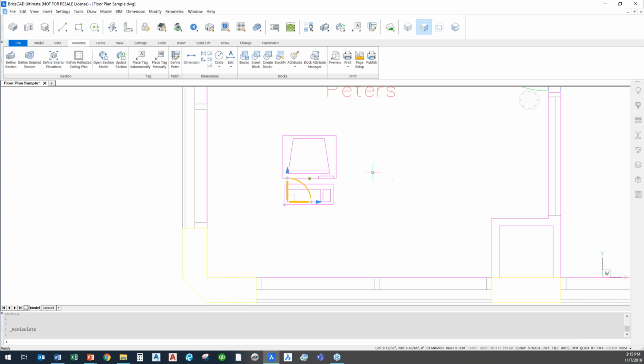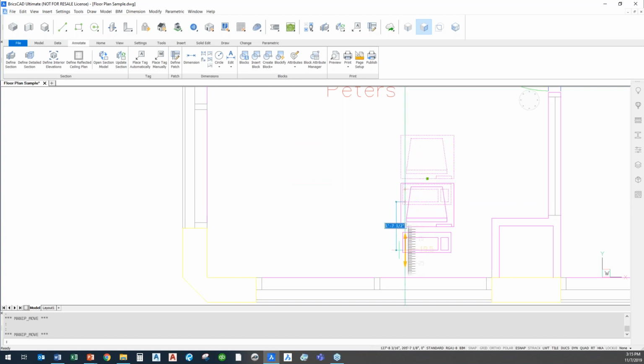For starters, you see that I have this little arc, so just by clicking here, I can spin around my origin point, no problem. Then I can go back here and, as I move from the top, I can move horizontally or vertically. So I can put in a set distance if I need to, just click that and move it 4 feet in that direction. And if I need to move it 2 feet down, I just click on the sidebar and move it 2 feet down, which is really amazing. The other thing that I can do, so that's nice when I'm moving things horizontally or vertically.